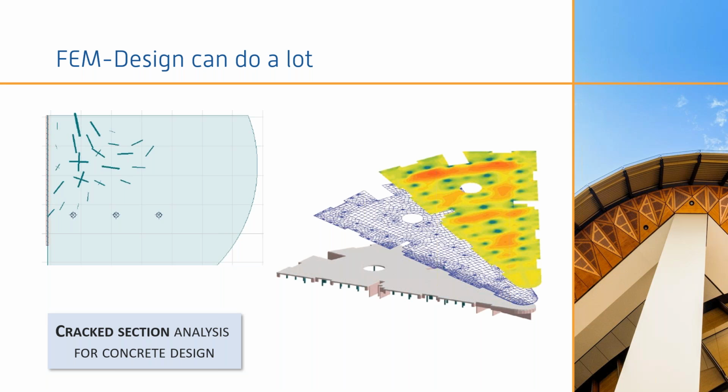A very powerful feature that I would like to mention in FEM-Design is the cross-section analysis for concrete design. We're not going to focus on this today in particular, but I wanted to mention it. You can perform a cross-section analysis on a concrete plate, for example, or concrete wall. After you have designed it and set some reinforcement into it, you can actually take that reinforcement into account in the calculation and study the cracks in the long-term behavior.